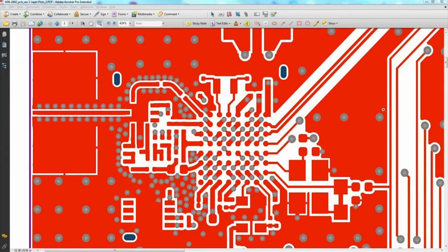Also, among some of the very critical considerations for constraints for RF layout are the lengths of traces. And really the question is if the lengths of traces are in the range of the signal's wavelength. Then the user has to consider the effects of transmission lines. The problems that a user must deal with are the time delay, reflections and crosstalk. To get a better understanding of these problems and where and how they arise, it's useful to know what transmission lines are.